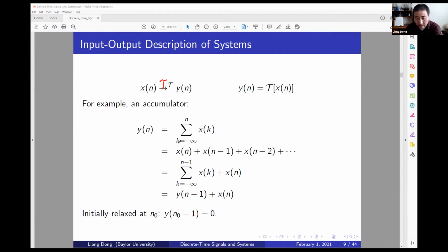So it looks like this. If you write this out, it can be spread out in the form of the second line. Look at the second line. What we can do is leave one x[n] here, and then the rest looks as if I am doing this, and it becomes y[n minus 1]. The only change is that I'm changing the time index from n to n minus 1. So it becomes y[n] equals y[n minus 1] plus x[n].